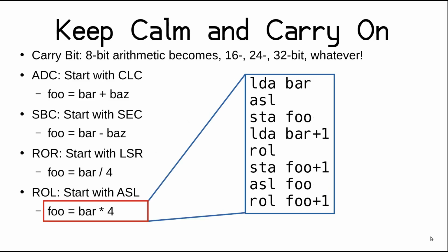When you shift to the left, you are effectively multiplying by 2 for each bit, as long as you are filling in the bottom with zeros. This can be accomplished with an arithmetic shift left, or ASL, on the lowest byte, and then using ROL, or rotate left, on each higher byte, which will shift in the bits that were shifted out of the lower bytes. If your top bit is already set, then the target of your shift will need to be wider to still have a proper multiplication. Generally, the product of the multiplication needs to be as wide as the widths of both factors put together. So two 8-bit values can multiply into a 16-bit value.